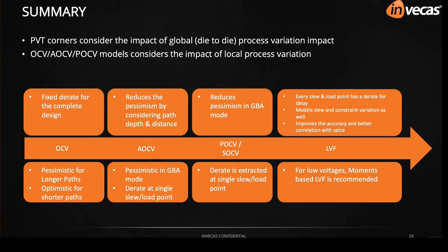To improve the accuracy, the LVF methodology has started, in which the derate value is modeled based on the actual load and slew values for a particular cell.